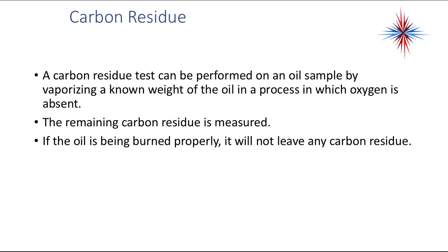So again, if we eliminate almost all oxygen as we burn the oil, the amount of carbon that's left is the carbon residue. But in normal, properly tuned oil burning furnaces and appliances, we should not have any carbon residue because we should always be giving it the proper amount of oxygen.